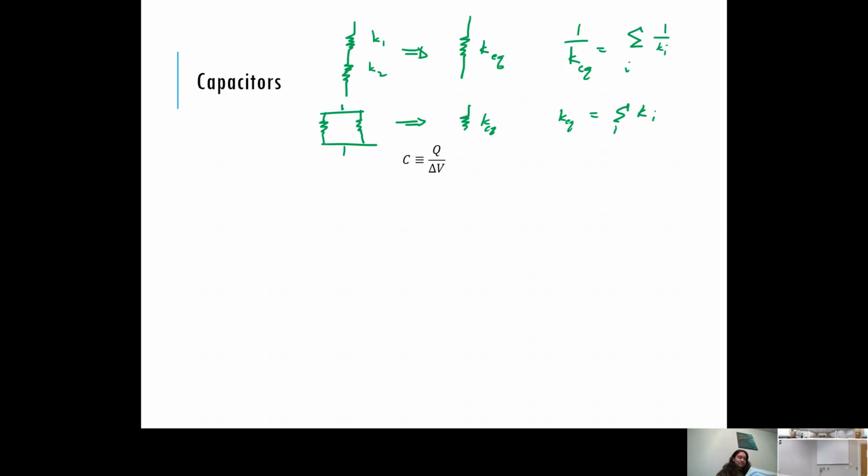And we'll forward track that knowledge because we will see this again with a different circuit element called resistors. Except the relationship's exactly the opposite. In other words, if you do it in series, they add, and if you do it in parallel, it's one over. Which is why I give you the warning: don't try to memorize it, think of the underlying idea and go by that. Because if you memorize it, you'll screw up resistors in series versus capacitors in series at some point, or you'll screw up the equation for capacitors in parallel with resistors in parallel. So just be careful.